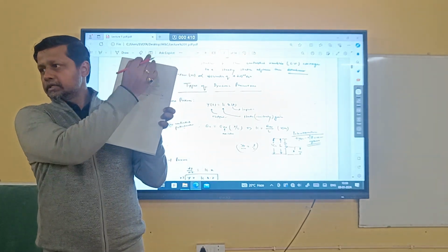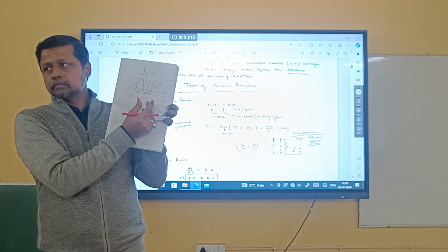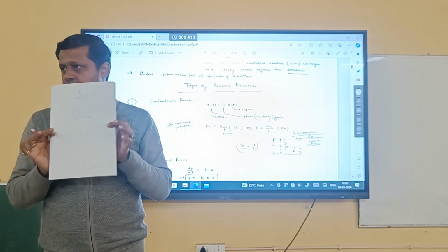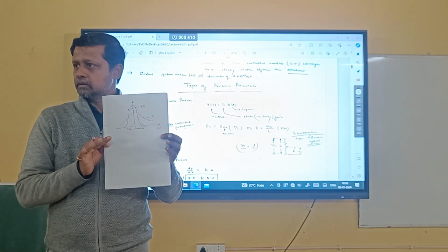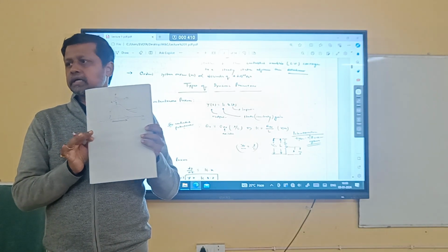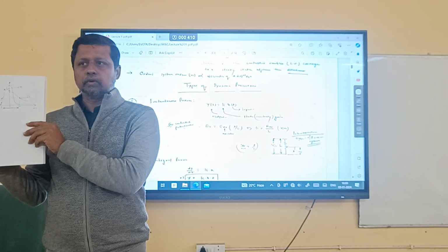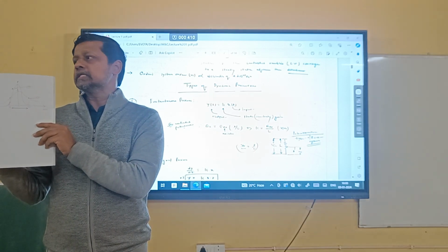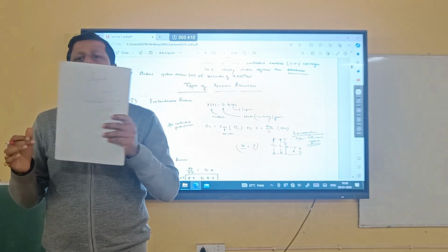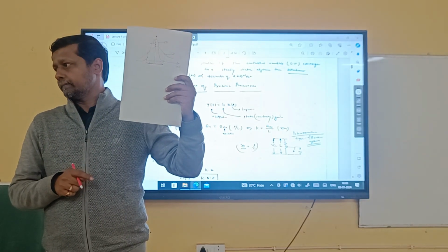Your Q factor is increased, no? Can I say that bandwidth has compressed? Both are the same system. So Q multiplied by bandwidth is offering the same information, but the characteristics are different. One is a little sloping, one is very impulsive, relatively more impulsive. Characteristic 2 adopts a higher rate of change as compared to characteristic 1.